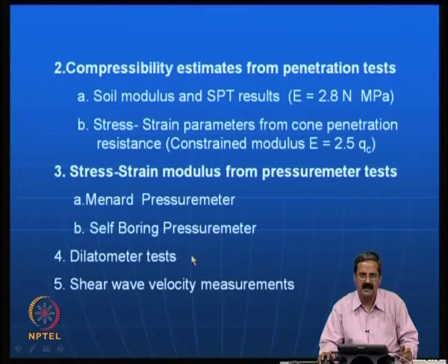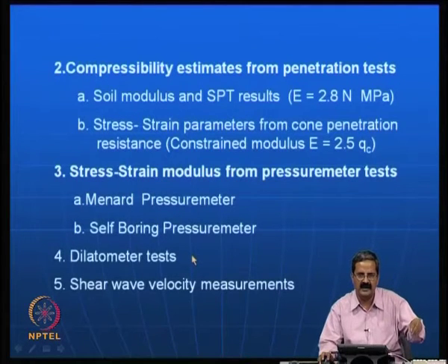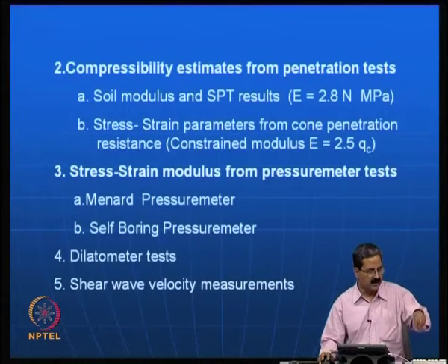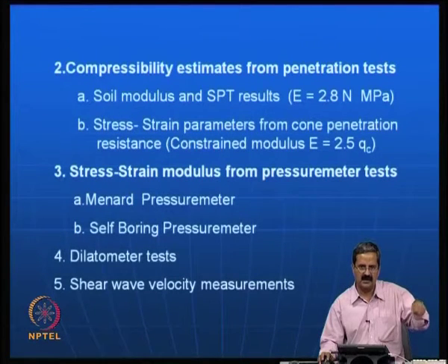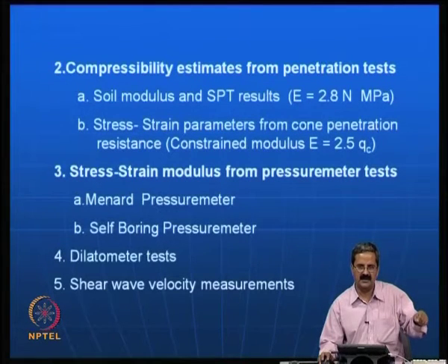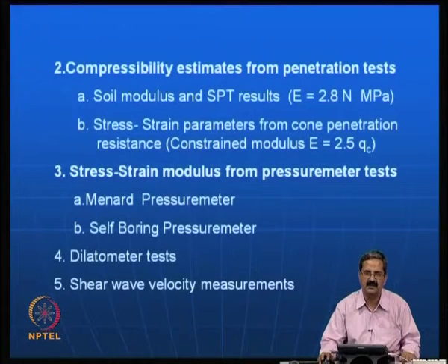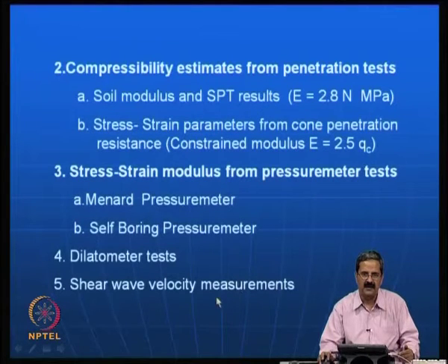They have a simple kit and one can use that. Here again the principle is that you put that instrument in a particular borehole and then you allow the diaphragm to expand, and resistance to deformation is measured. The diaphragm starts expanding because you will be applying some sort of pressure. The pressure versus the deformation is recorded, and so you will get a lot of information from both the tests, because the advantage is that you do not need to take undisturbed samples, you are getting the response of the soil from the undisturbed state itself. There are also some more measurements on shear wave velocities which is very popular, we will see some of them now.